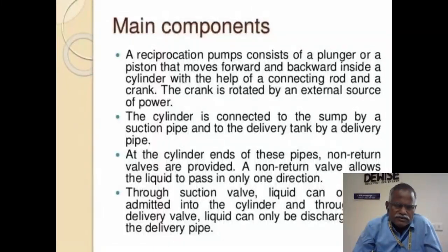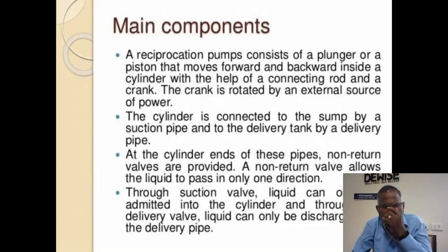At the cylinder ends of these pipes, non-return valves are provided. The non-return valves allow liquid to pass in only one direction. Through the suction valve, liquid can only be admitted into the cylinder. Through the delivery valve, the liquid can only be discharged into the delivery pipe.